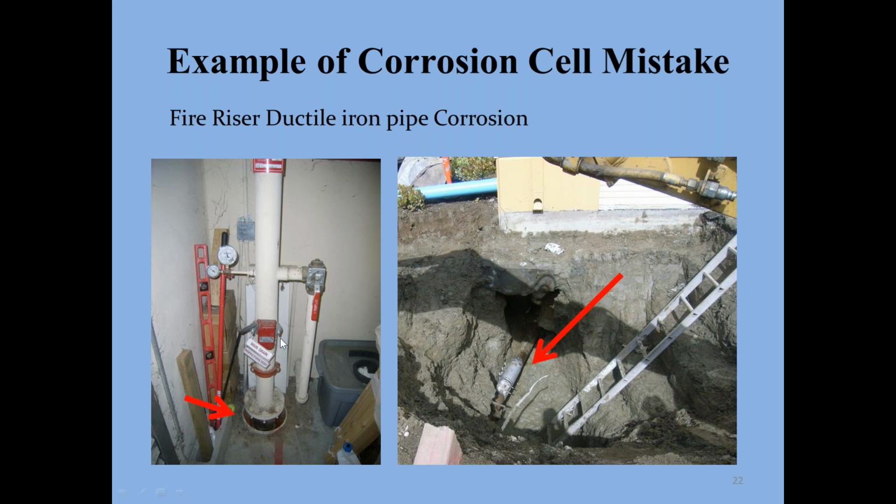And once it's in the building, there are a lot of meters connected to it, and a lot of electricians like to ground their equipment onto these pipes and so forth. And somehow it ends up also shorted to copper water piping in the building.